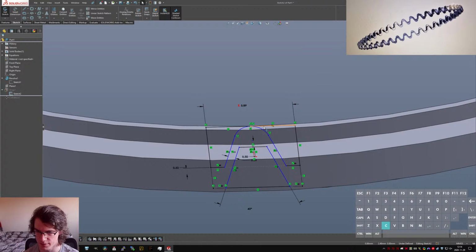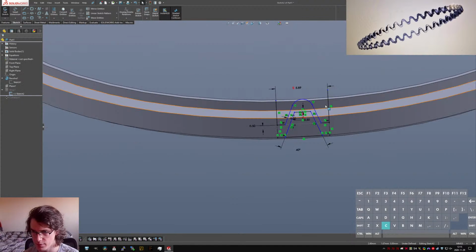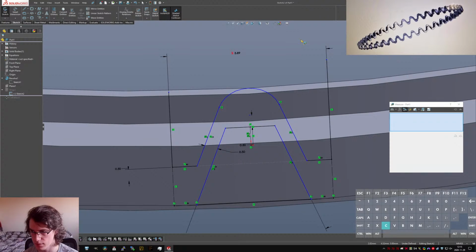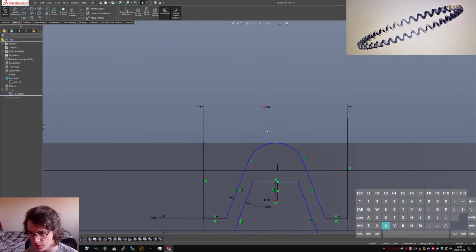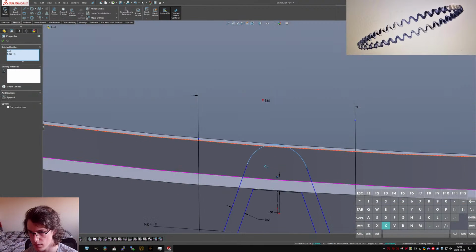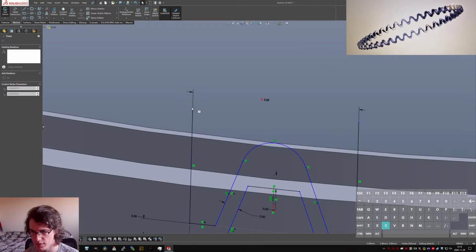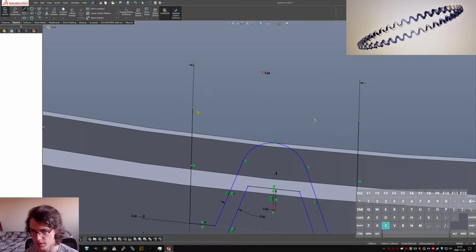Now I have sort of a conundrum. Here's what I'm going to do instead. I'm going to bring these two up. I think, what are these guys coincident with? Okay, they're coincident with that line. What I'm going to do instead is end to normalize. I'm going to make this guy tangent with that, well, yeah, tangent with that edge is fine. And then I can come up here,